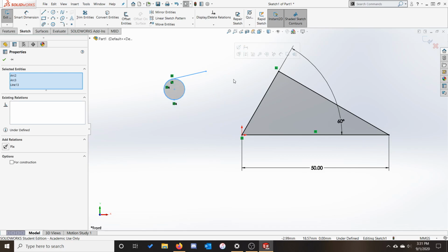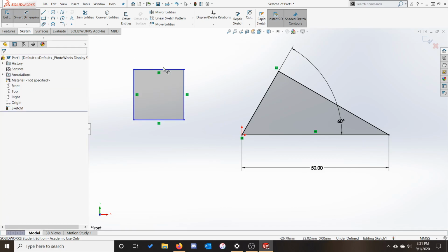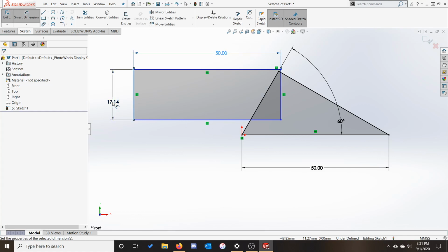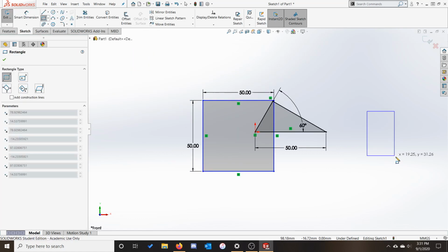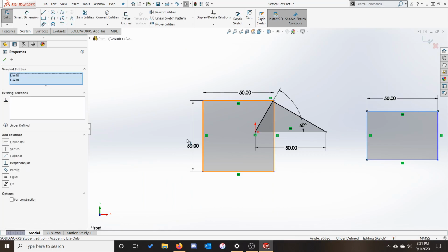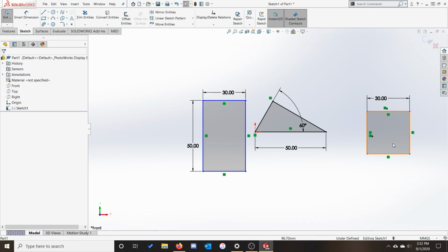A lot of relations are based on design intent. For example, there's a difference between drawing this, a square where we've defined both sides to be 50 units long or tall, respectively, and drawing this, a square where we specified that one of our sides is 50 units long, and the other side is of equal length to the first side. In one circumstance, if we change the width from say 50 to 30, the height remains the same, whereas in the other one, if the dimension's been changed, all of the edges are changed to match.